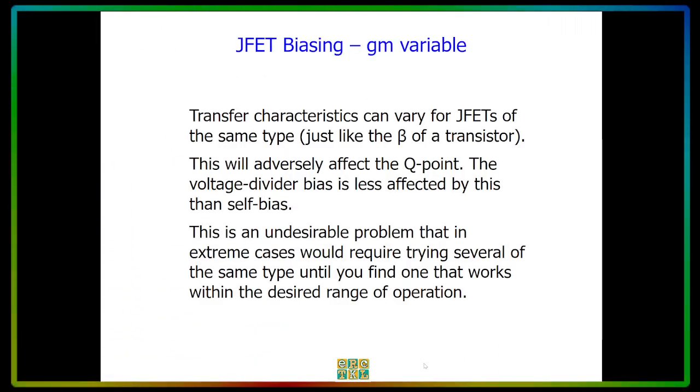The transfer characteristics can be different for JFETs of the same type, just like the beta of a transistor, and the effect will be big for the Q point.